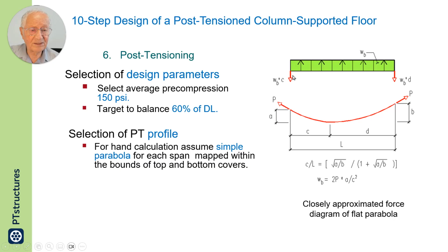In design, because typically the length is much more than the drop, it is assumed that the force is applied upward and it is uniform in magnitude. It's a close assumption and it's universally used. So there will be an uplift assumed uniform, and its magnitude is given here. The magnitude depends on the geometry and the force.